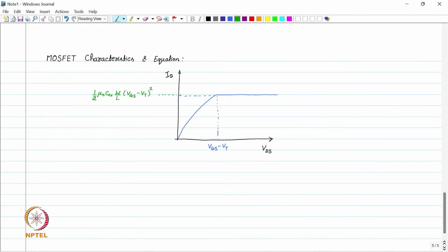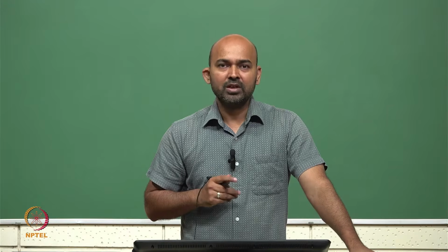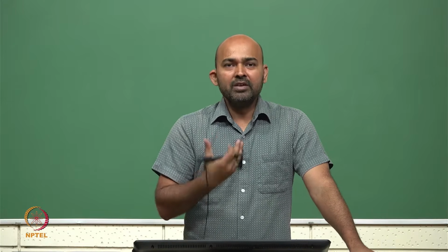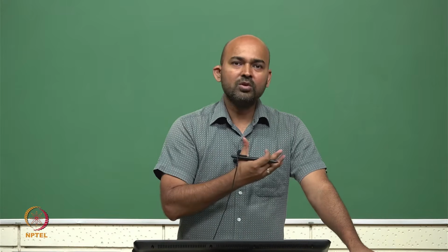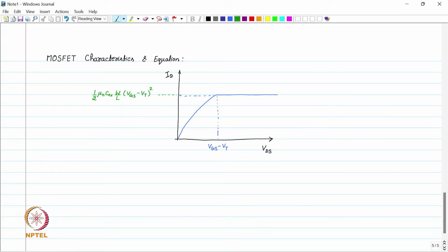But as we keep on increasing the voltage, at some point there are not enough charge carriers in the channel which we can pull away by applying high voltage. So even if we apply the high voltage, there is no charge carrier, so the current will not increase. The current is going to saturate at some point, even if we are applying higher and higher drain voltage.